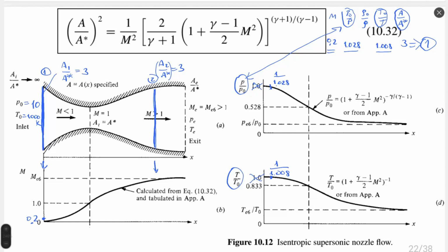Okay, but this formula is created in Kelvin because of convention of units, and because for calculation we are using dimensionless Mach number. So temperature ratio is also should be in corresponding units, and this is a ratio of Kelvin, not other temperatures. But we can calculate in other temperatures.